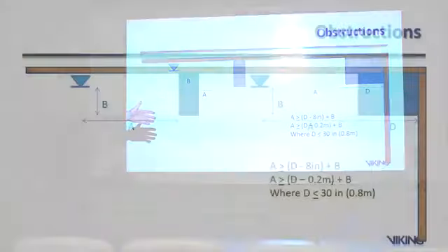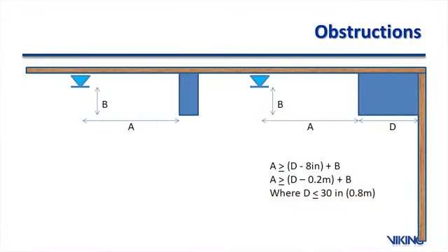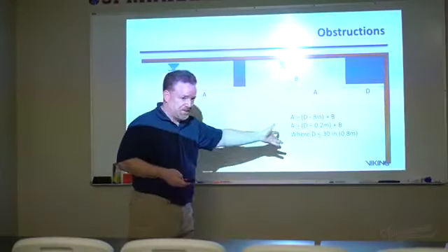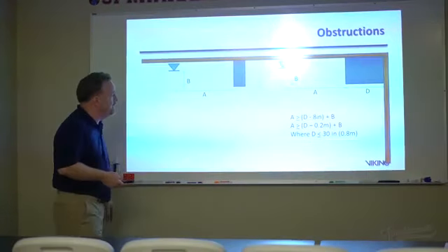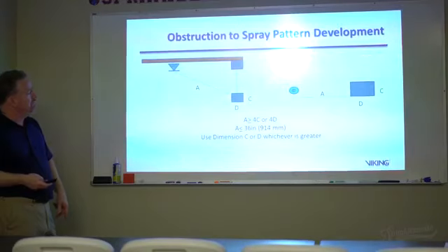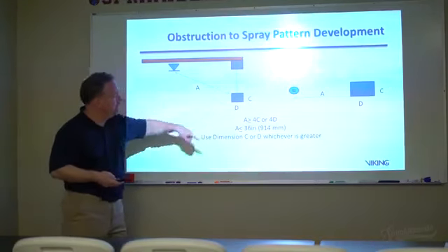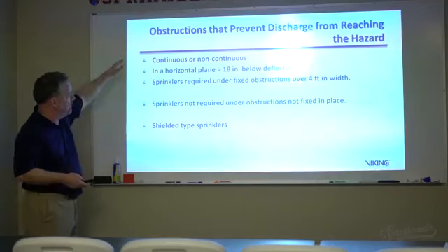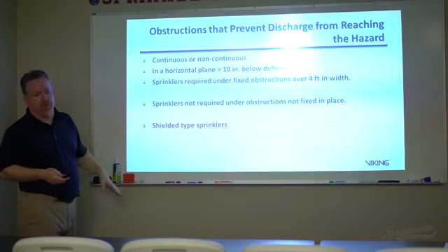Seen this before, all right? The beam rule applies, kind of like extended coverage, because remember we showed you the spray pattern looks the same, all right? The spray pattern is the same. 4-foot obstructions, the 4 times rule, and all of the same rules.